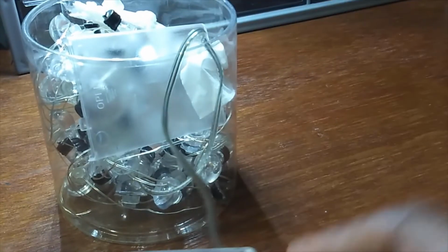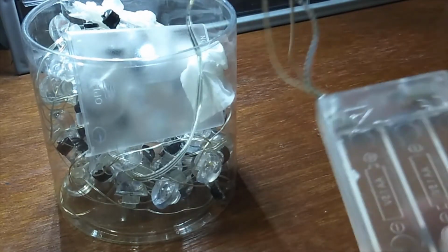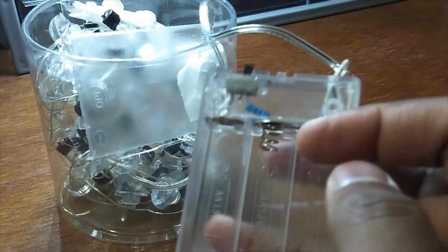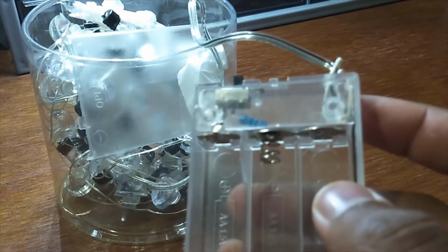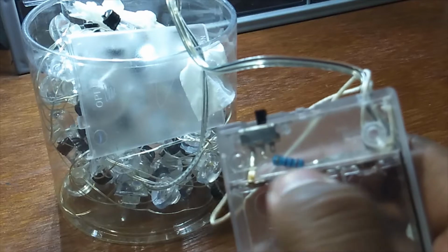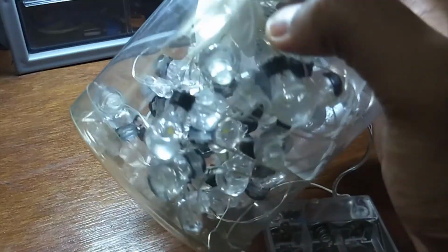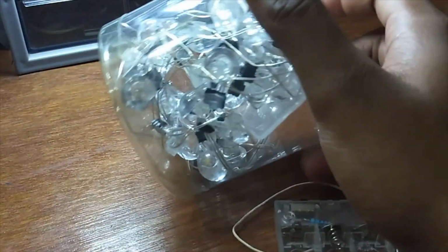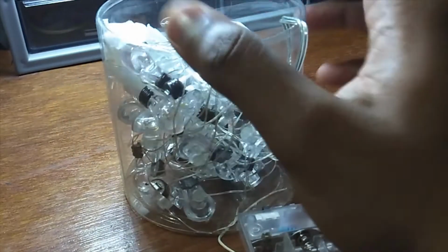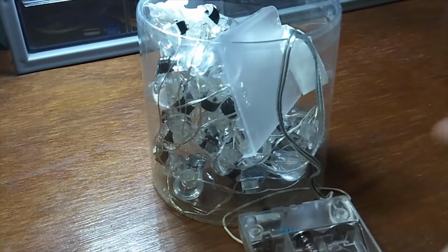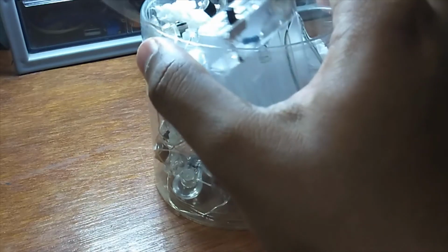The second thing would obviously be some LED or light arrays, right? So this is something that I'm going to use for the light arrays part of it. This is a light that basically used to work on three AA batteries. It had a built-in internal resistor for current limiting, and then it goes out in parallel to all these LED arrays. Those are all connected in parallel, and they light up. It's going to be a warm white color. So this is an example load that we'll be using to drive the circuit.